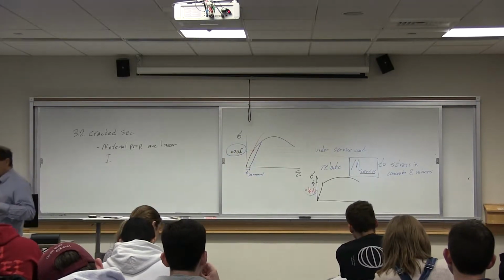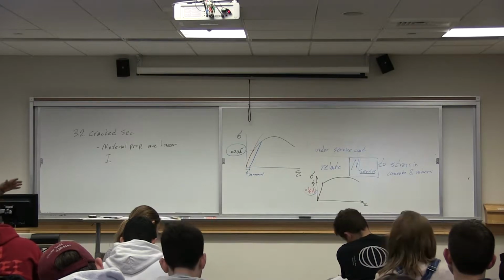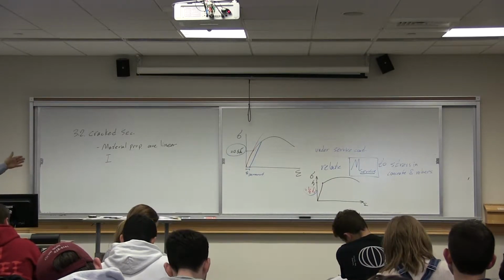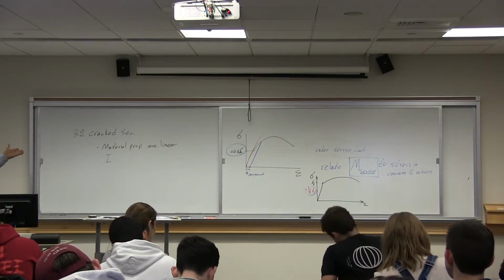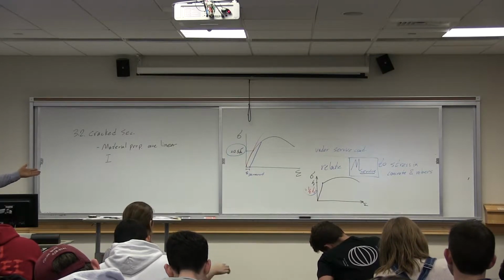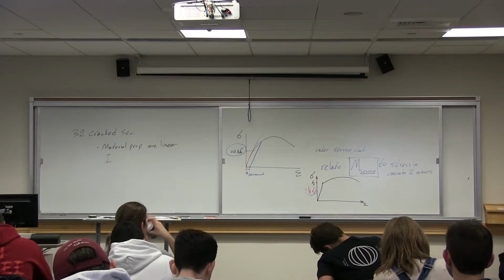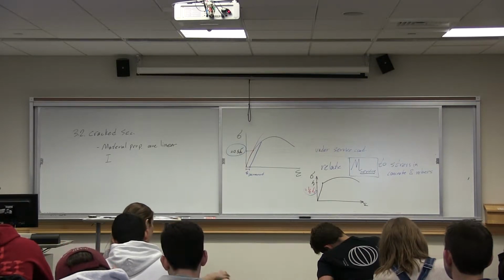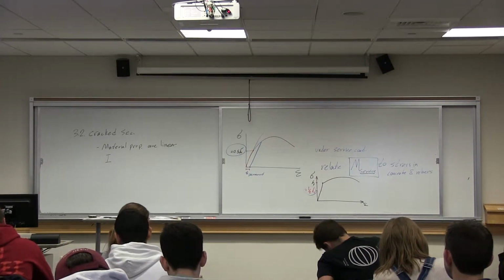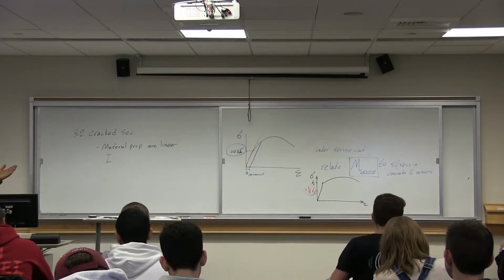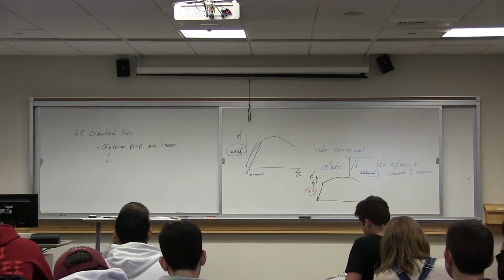We are not saying a reinforced concrete section should not have a stress in concrete more than 1/2 of F prime C or in rebar more than 1/2 of Fy. That's not what we are saying. We say under service condition, that's what we say as a limit, not under exceptional cases or extreme loading conditions.